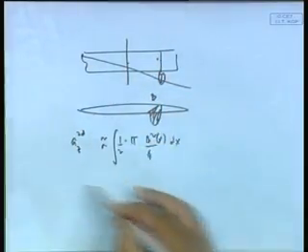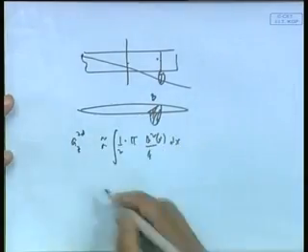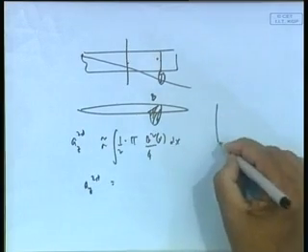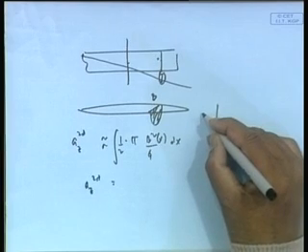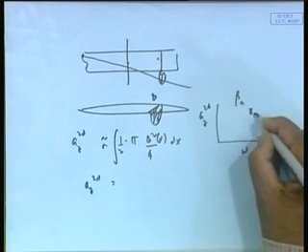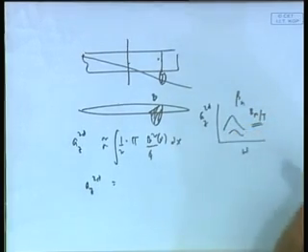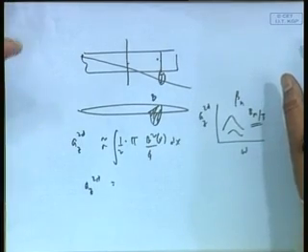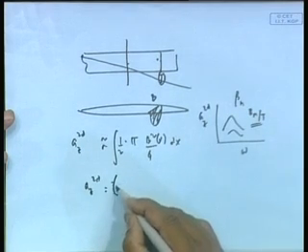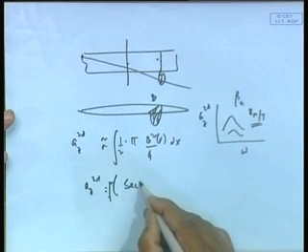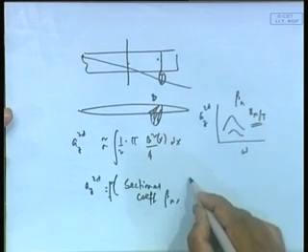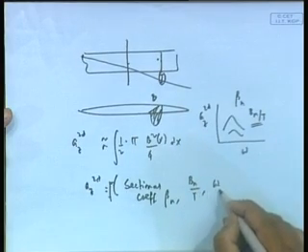So, here also we can make a very rough guess. If not, as I mentioned in yesterday's class from that Lewis form, there are graphs and charts where these sectional values are given for different values of beta n and b n by t, etc. Various graphs are given, as a function of sectional coefficient beta n, then coefficient b n by t, and of course omega e.